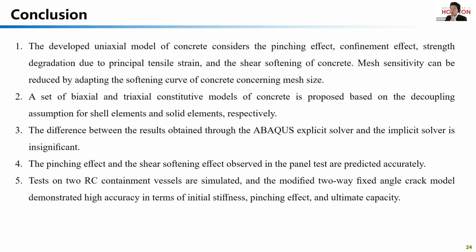The following conclusions can be obtained. The first, the developed uniaxial model of concrete considers the major effects of concrete in hysteretic loading, and the mesh sensitivity issue can be reduced by adapting the softening curve of concrete, considering mesh size.